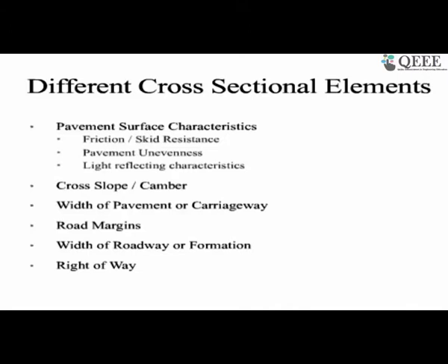Now, sometimes your road may need to be elevated from the basic ground profile. If it is elevated, you need to provide a side slope of 2:1, or depending on the soil characteristics, which means the width of the roadway on the top is not going to match the bottom or the base. So it's going to be different.